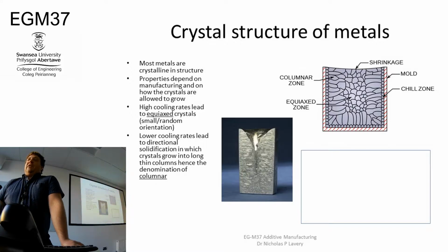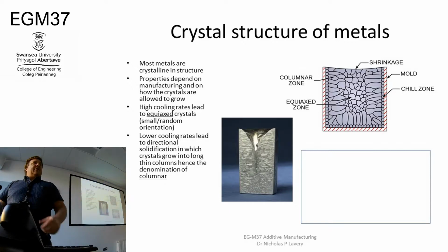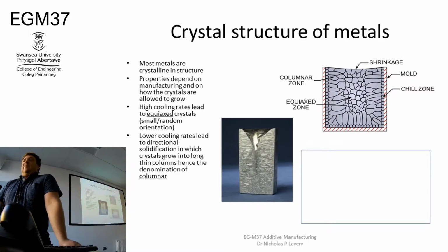So you get equiaxed and columnar, which are the main two types of crystal. When you get a very rapid reaction, very small crystals form and nucleate close to the cooler boundaries. Then you've got a slower solidification, with the cooling rates tending towards the middle, where it finally solidifies. And you can see the predominant direction that the crystals take in this bottom image animation here.